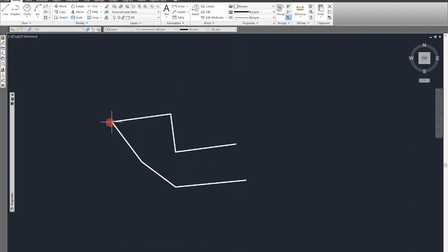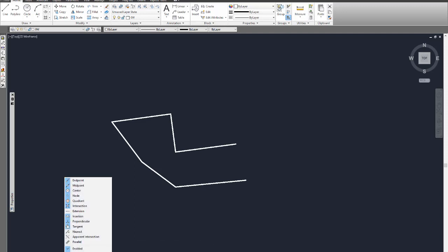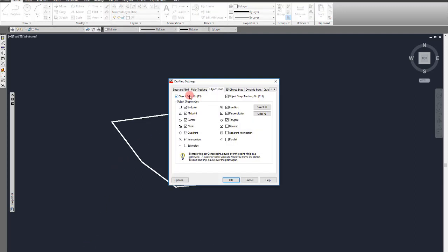Now in drawing I will explain this because you see it always when I draw. You see some signals when I start drawing, like this green square here, green square, and green rectangle. And you may ask, what are these? These are the snapping specific points of the geometry. Like if I go here, object snap, and right click and go to settings, you can see the snapping points.